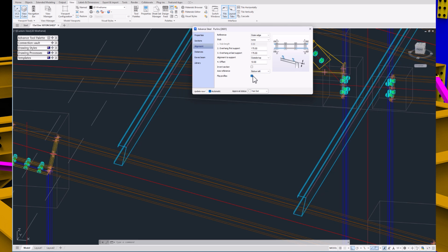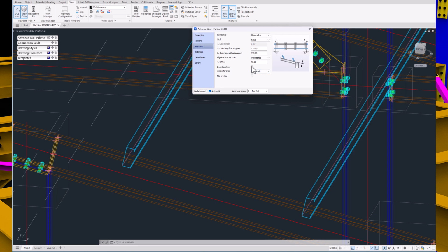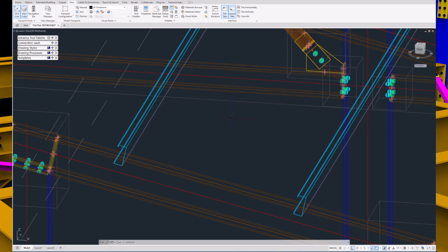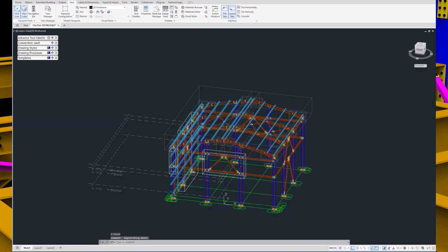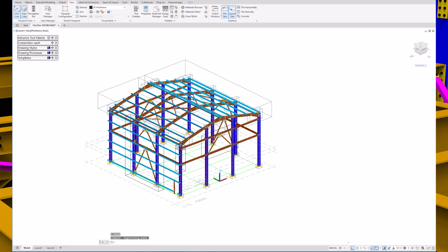If you say flip, it changes the location of your axis line, but the position of the pay line does not change. The orientation has been changed, and also the axis line position has been changed. We don't want to change the axis line position because this is also good for us in terms of editing. So I'm just going to invert the section. Okay, so this is what we want to do, and we are done.